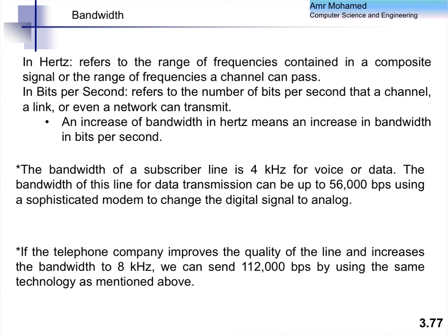How many levels did I use here? Someone calculates it and gives us the answer. All right, so basically, this is calculating the bit rate based directly on the actual bandwidth of the channel. If I were to use Nyquist here, I can use a certain number of levels to achieve this bit rate. But again, this bit rate is theoretical.